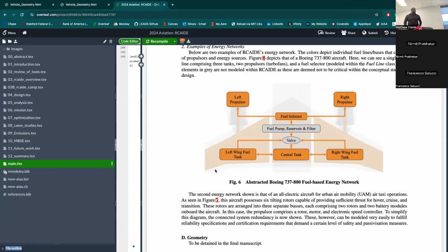So you have something called a propulsor, and a propulsor is pretty much a class that contains components that generate thrust, right? A propulsor right here, as you can see, and I painted it in the back. A propulsor, for example, is a turbofan engine, or a propulsor could be a motor and a propeller combined. That combination provides thrust. Do you guys understand that?